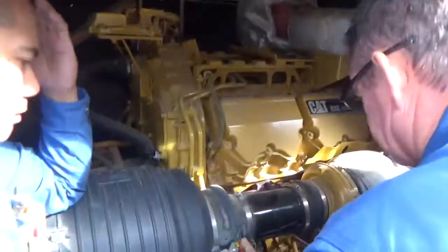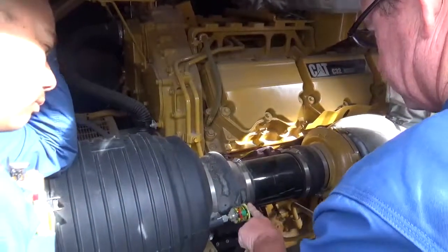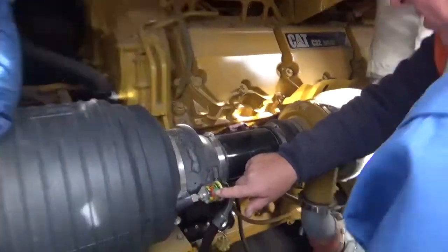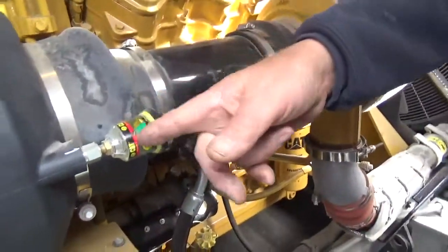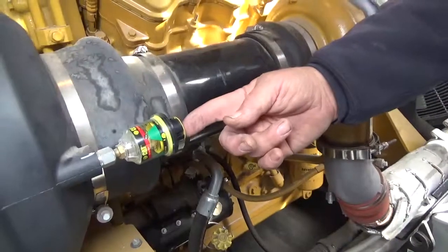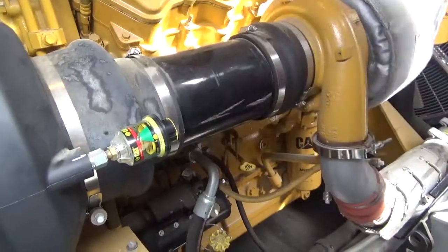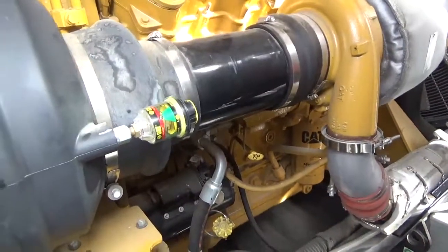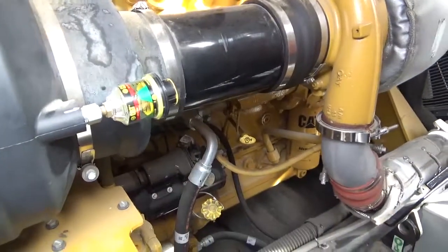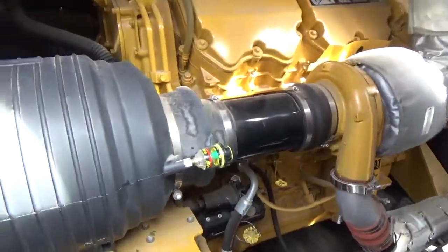This is normal position, right? Yes, that's the okay position. Yeah. All the way up. It'll suck down this way here, and when it goes red, obviously you need to fix it. So, and to reset it, you just push on the end button, and it'll click it and send it back. What does that do? That's the air cleaner indicator. It tells you if the air cleaner's getting plugged.